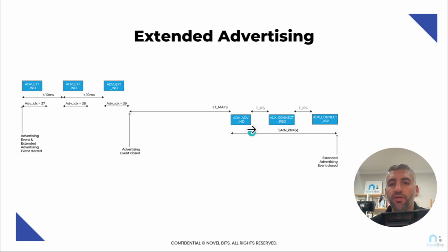know where to find this one, which is supposed to be AUX_ADV_IND, not ADV_ADV_IND. That's a typo on my end. And then from there, it can send the AUX_CONNECT_REQ and then get a connect response.